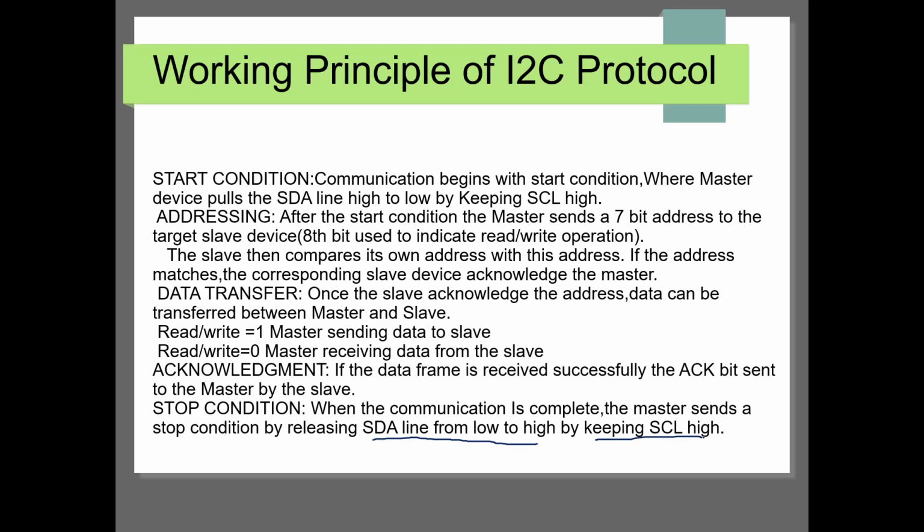I told you, right? For the start condition, it happens while the SCL line is high and the SDA line is pulled from high to low.